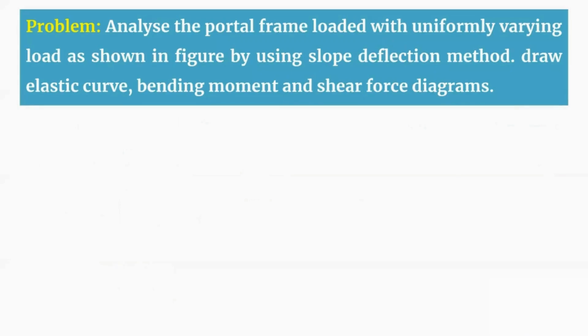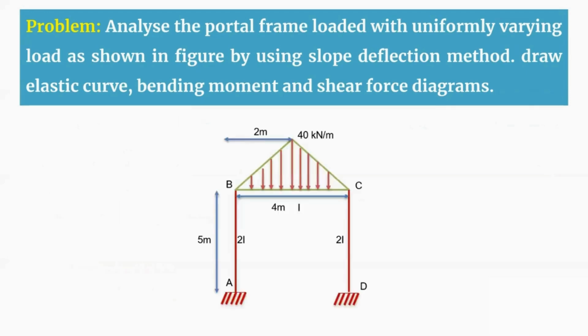So here you are going to analyze the portal frame, which is loaded with a uniformly varying load as shown in the figure, by using the slope deflection method. You're going to draw the elastic curve, bending moment, and shear force diagram. So this is the figure for this portal frame that you are going to analyze.